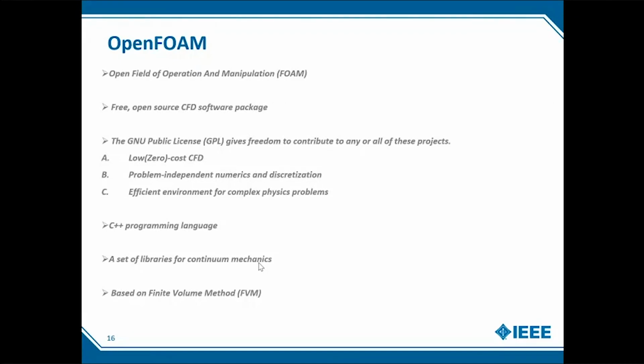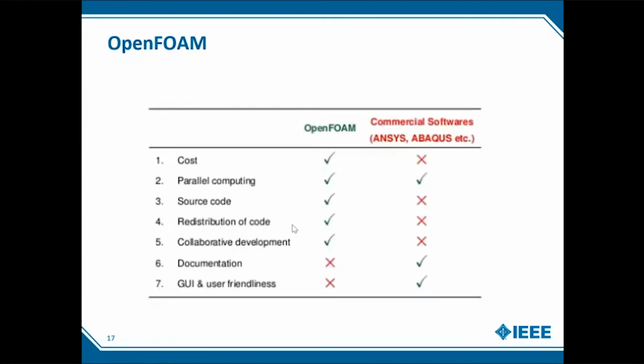We have to consider the mean free path of each of the fluid molecules, etc. Such a system cannot be simulated in OpenFOAM. So your continuum mechanics assumption should hold when you're using OpenFOAM. And OpenFOAM is basically written in the C++ programming language, so it's very essential to know C++ if you're using OpenFOAM.